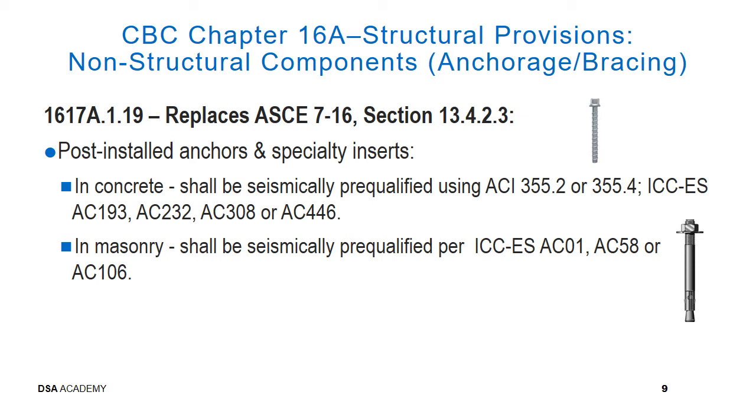Post-installed anchors and specialty inserts to be used in concrete shall be seismically pre-qualified using ACI 355.2 or 355.4 or ICC-ES Acceptance Criteria AC193, AC232, AC308, or AC446.